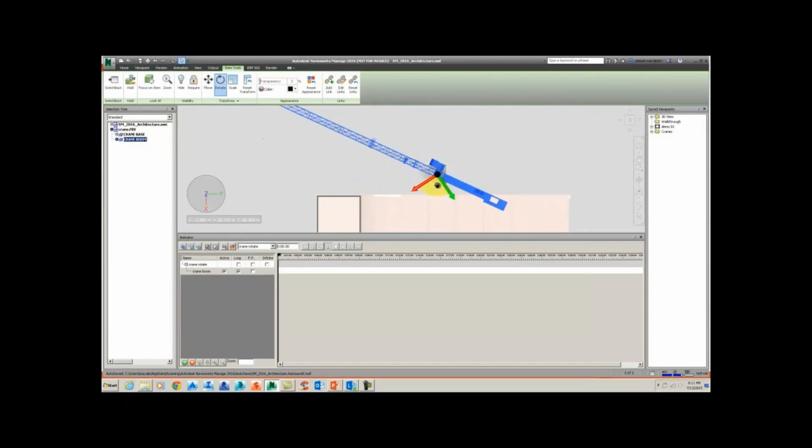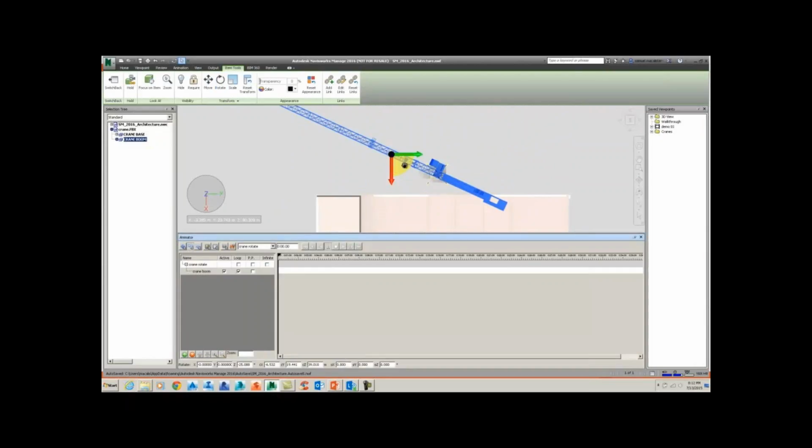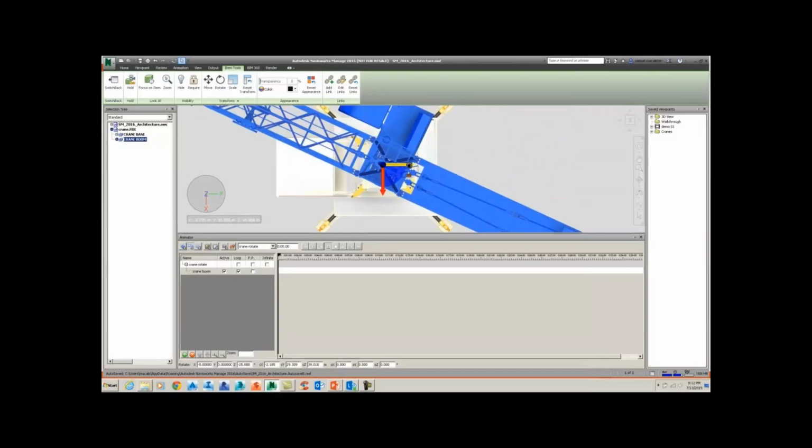So I now know that wherever I'm wanting to place that crane or cranes, and if I need to rotate it around, I know the extent of that crane boom. It's not going to clash with anything. You know, there's all these things that you got to be aware of on construction sites. It could be overhead power lines, neighboring buildings, lifting items over fences or over walls.